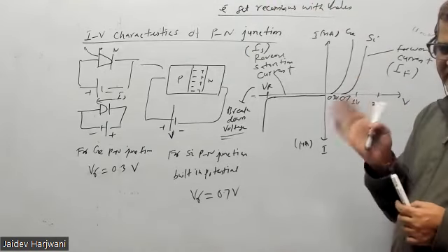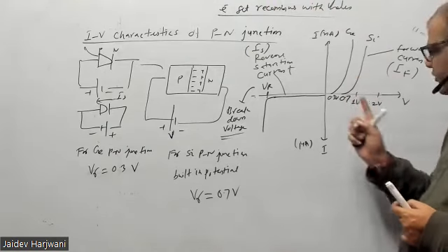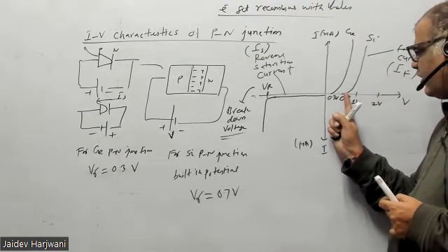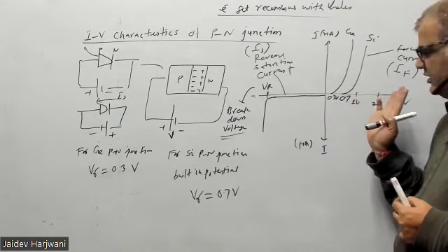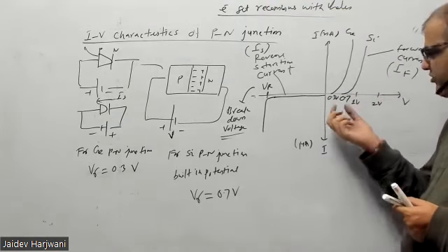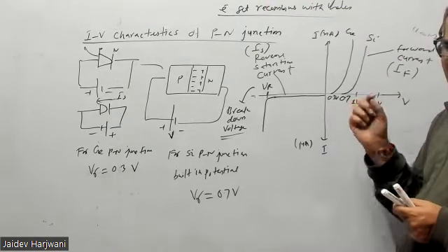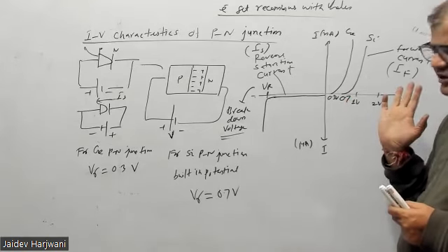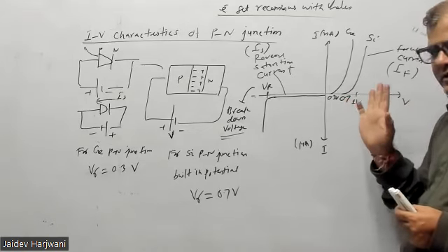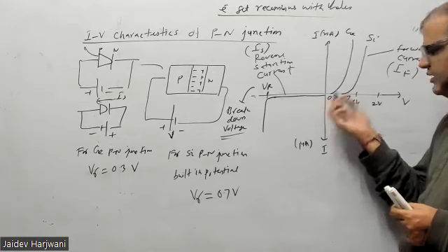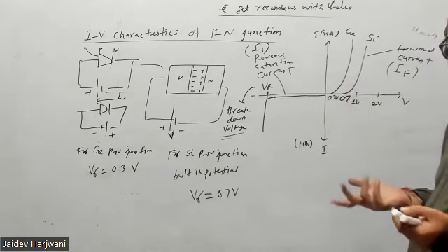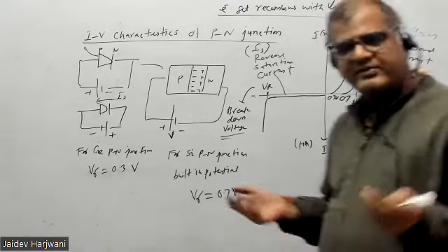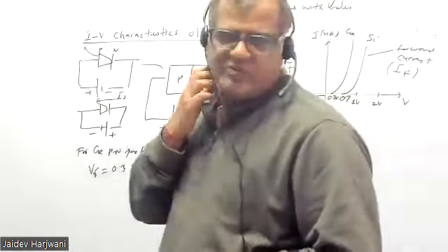While you are dealing with a diode in a circuit, you can assume that the drop in potential across the diode is always constant. If it is silicon, the voltage drop across the diode will be 0.7 volts, always. If it is a germanium diode, the voltage drop will be 0.3 volts. Like resistors, when you apply some voltage, some current flows, and some voltage drop should be there.